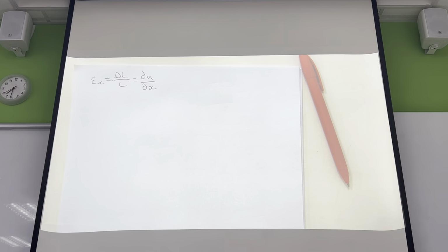So if I have this pen and I just move the whole thing 1 meter over this way, there's no strain in that system in the X direction, because this point's moved by 1 meter, that's moved by 1 meter, that's moved by 1 meter. But if I was to hold one end fixed and then pull the other end, then this end would have displacement 0 meters, and there'd be a rate of change of displacement as I move in the X direction. So strain fundamentally is the rate of change of displacement in the X direction with respect to the X direction, du dx.